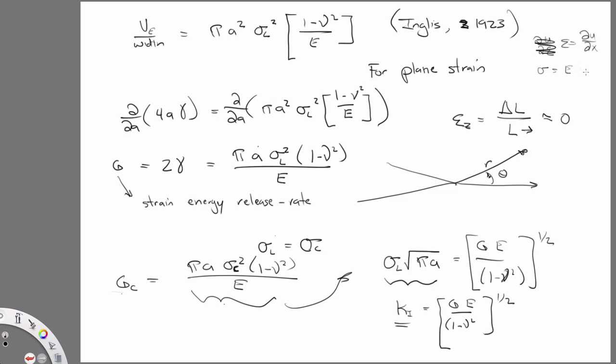In the simplest case for elasticity, stress is like this. So stress is also a function of the derivative of displacement, which is undefined at the tip of a crack. According to this theory, this means stress is actually infinite at the tip of a crack. Well, we know this is not physical.